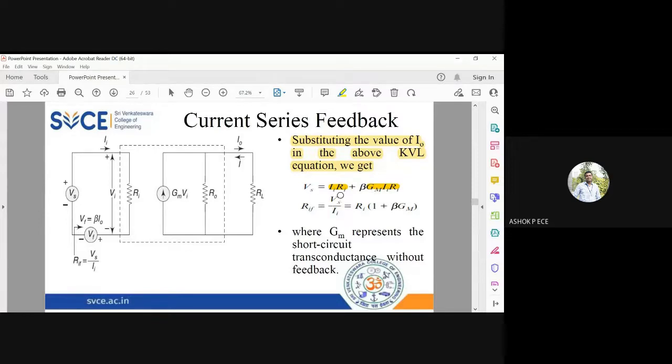So Vs by Ii will be equal to Ri into 1 plus beta GM. You know Vs by Ii is Rif. So Rif equal to Ri into 1 plus beta GM. So whenever this Ri is multiplied by a big term, the input resistance with feedback is going to increase a lot.